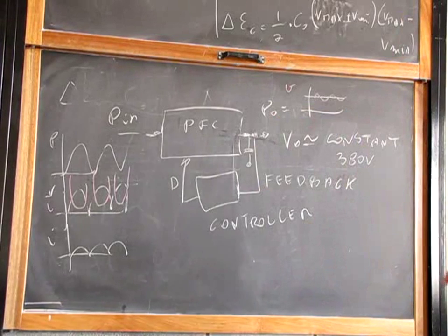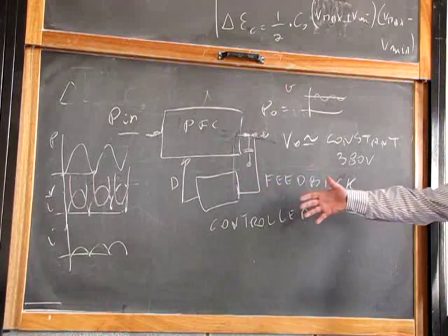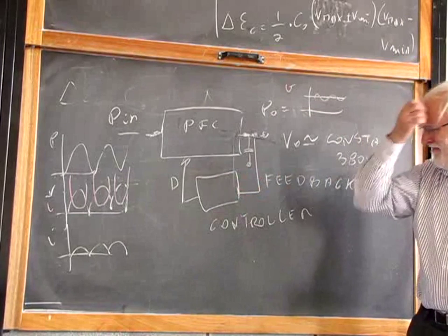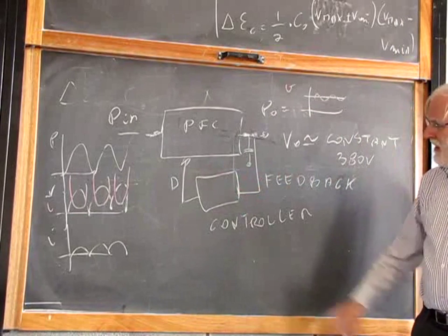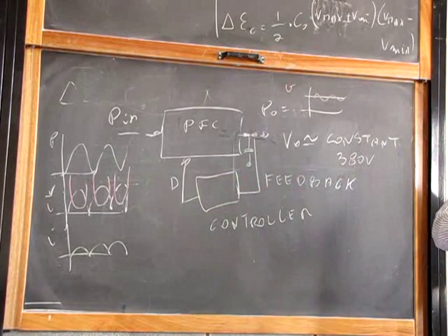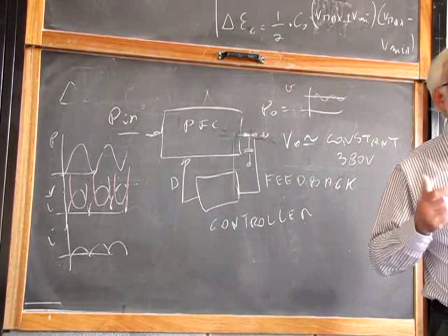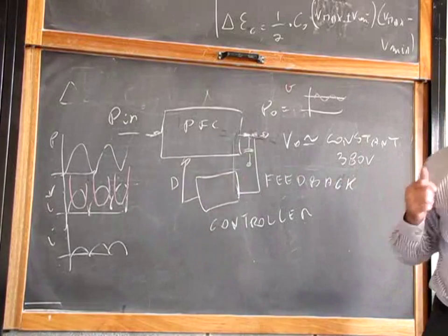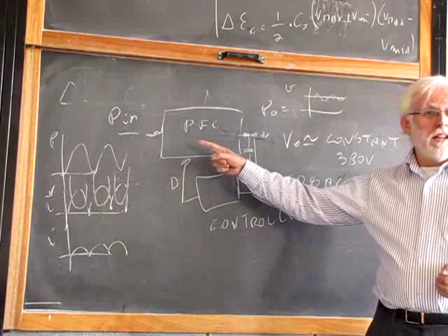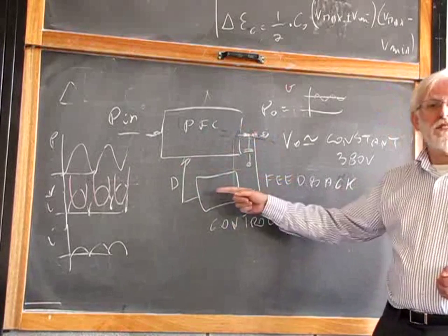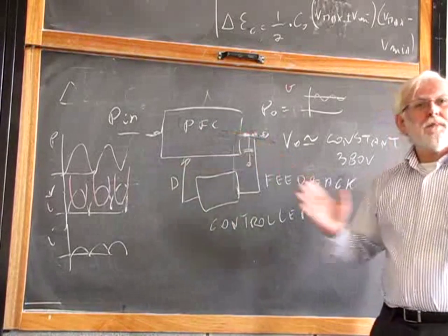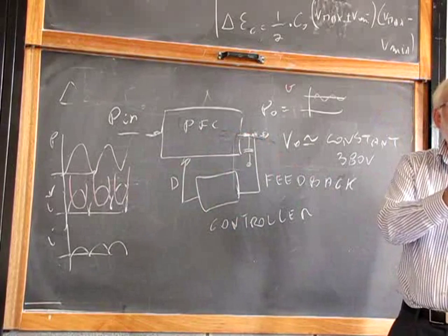Low pass filter. Well, a controller is a filter, basically. We will learn how to design these controllers. But what happens is that this feedback must be there for the DC and must not be there for 100 Hz. It means that the bandwidth of my control system, the bandwidth of my loop gain, the bandwidth of my return ratio, I don't know if you call it loop gain or return ratio, or fine. This bandwidth must be narrow, must be 10 Hz maximum.